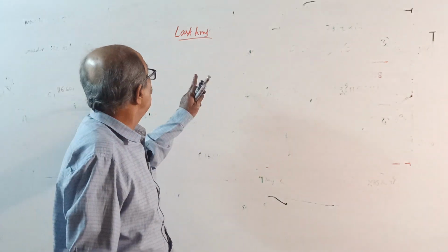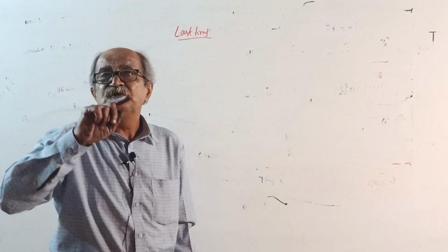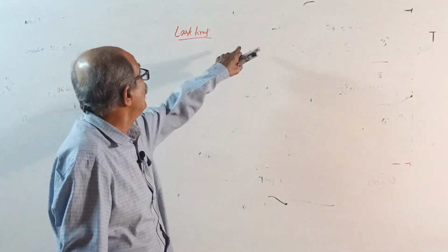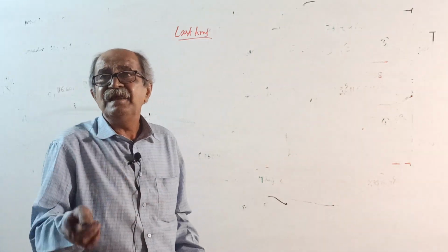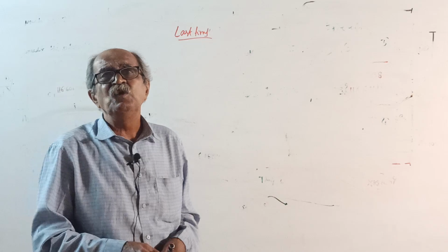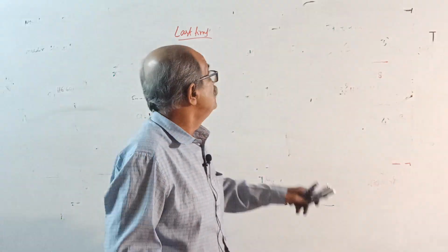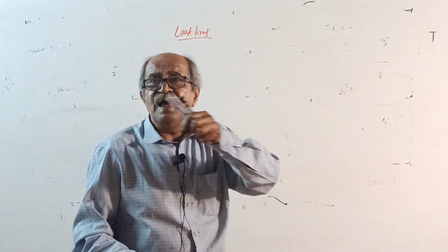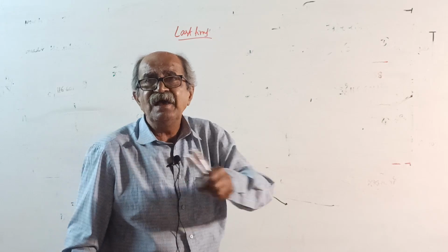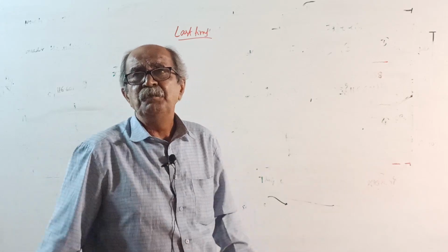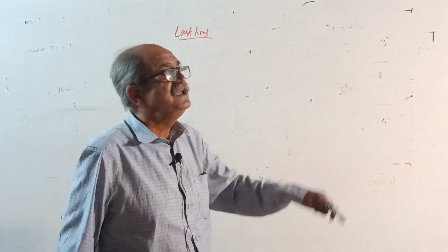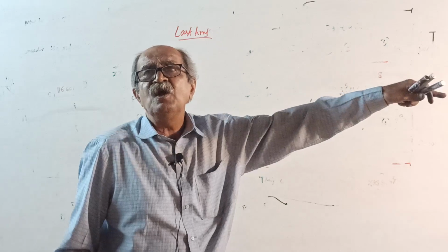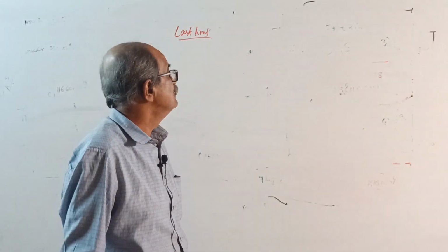But in the same question, if they ask I about some other axis, since you already got I about the centroidal axis for the entire lamina, don't once again go to part by part calculation. You use that one. Write a sketch marking the centroidal axis and also the required axis and transfer it by parallel axis theorem using the already calculated moment of inertia about those centroidal axes xx and yy.